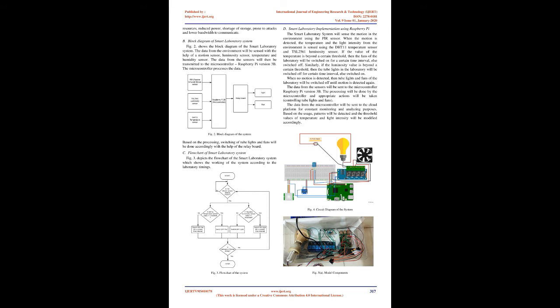The Smart Laboratory System will sense the motion in the environment using the PIR sensor. When the motion is detected, the temperature and the light intensity from the environment are sensed using the DHT11 temperature sensor and TSL2561 luminosity sensor. If the value of the temperature is beyond a certain threshold, then the fans of the laboratory will be switched on for a certain time interval, else switched off.